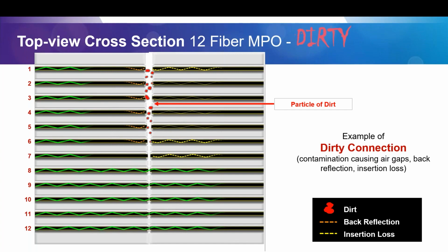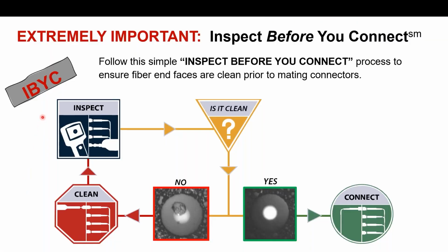Let me show you what we do. This is a VIAVI thing. It's drilled into us: inspect before you connect. So we always say inspect the fiber, don't clean it. The habit that I see most of the time is you go out, the guy grabs his one-click cleaner, and before he plugs something in, he just cleans the heck out of it and plugs it in with no inspection.